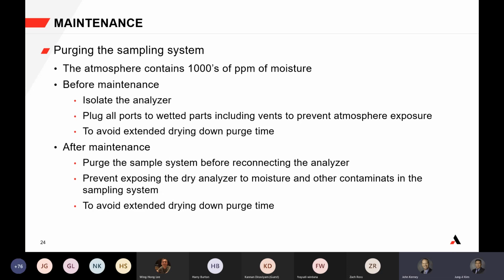Okay, and the motivation for the question was, since we're not to have any flow control before the analyzer, that was the reason for having a valve downstream of the analyzer in order to be able to set flow. Okay. Most analyzers that I know of, except for I think aluminum oxide, where you have to set the flow, with the exception of aluminum oxide, all other analyzers have flow control within itself. So you just have to provide the required sample pressure, and it will do the rest.